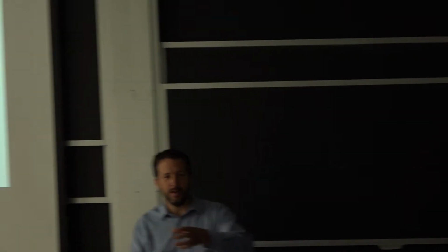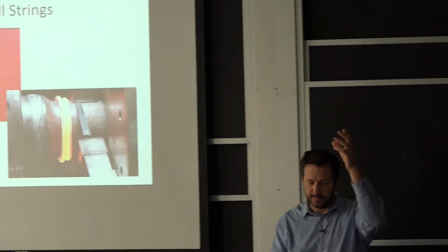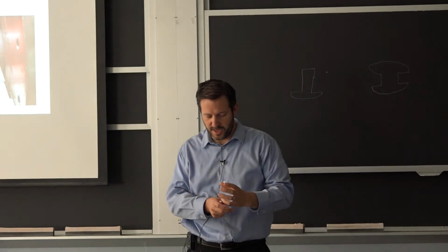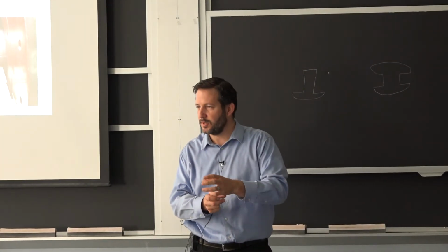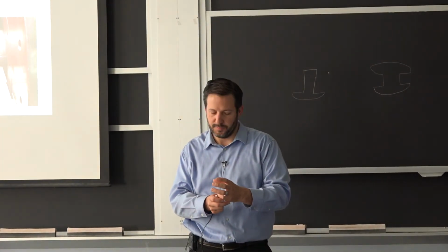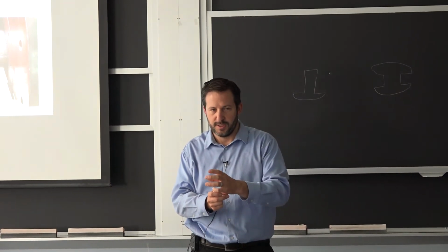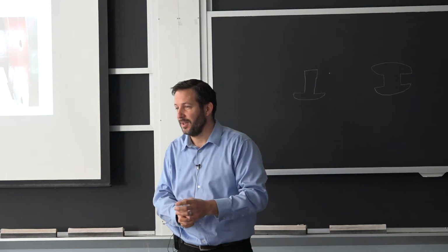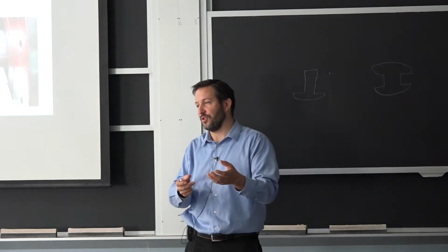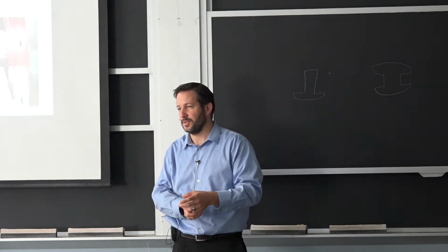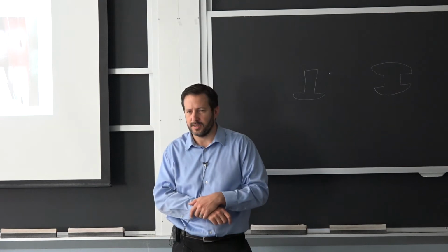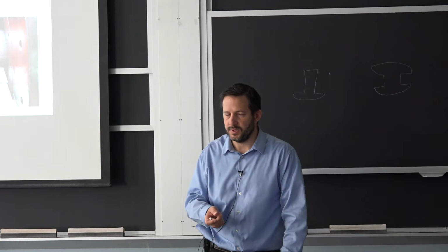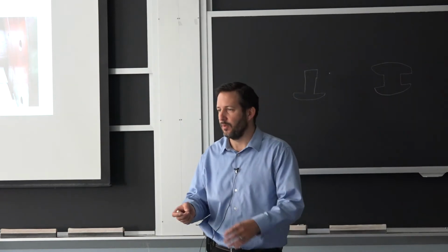See, if you have a very, very long string from the barge on the ocean down to the seabed, this last piece close to the bottom of the ocean sometimes needs to be able to deform and actually change shape. And you don't put just a hinge there because you need to be carrying the fluid. So they were working on special titanium alloy just for their fatigue resistance, so their ability to deform repeatedly.